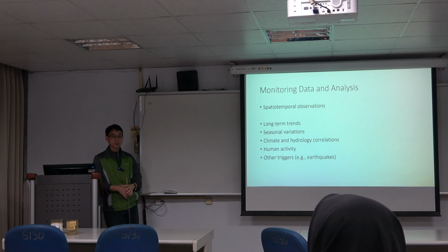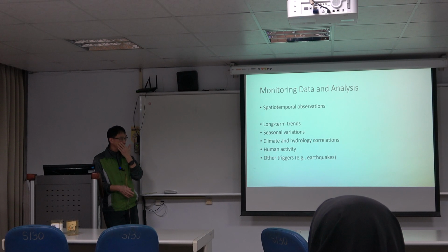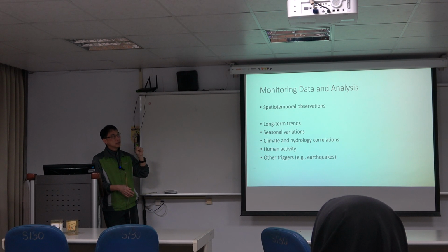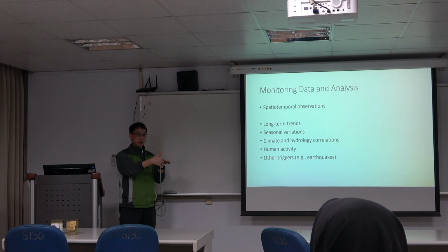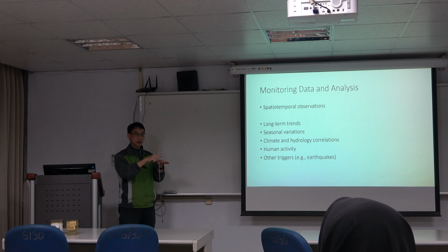Another could be liquefaction. In the Chi-Chi earthquake events, we can see that at the foot of the Zhanghua foothill, liquefaction occurred. We guess that area is mainly due to this kind of behavior, because the foothill area is relatively high, and we can see a lot of groundwater level decline. The decline means that the water needs to flow out, so it flows to the foot of the foothill areas, becomes a kind of upward flow pattern, and induces liquefaction around that area.